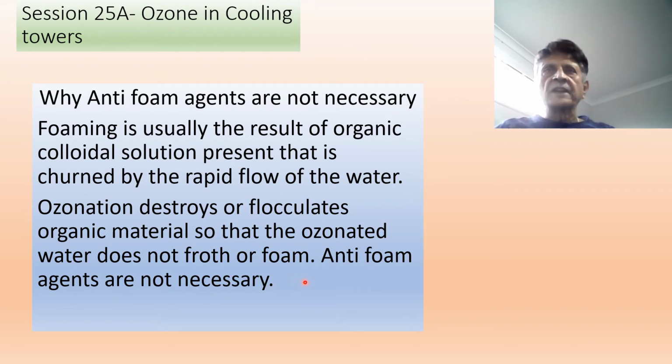If by chance anybody adds any material or any chemicals that contain organic materials or organic chemicals, then the foaming will start to happen until such time the ozone destroys the organic material in the chemicals that is added, and then the foaming will stop forming.